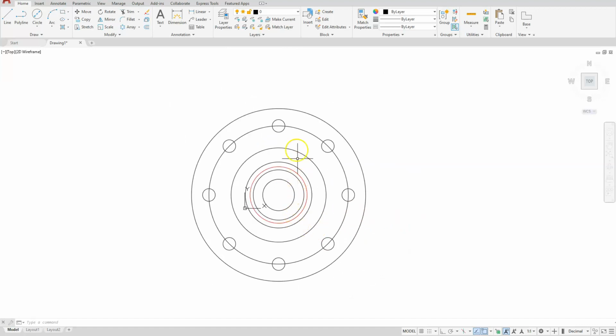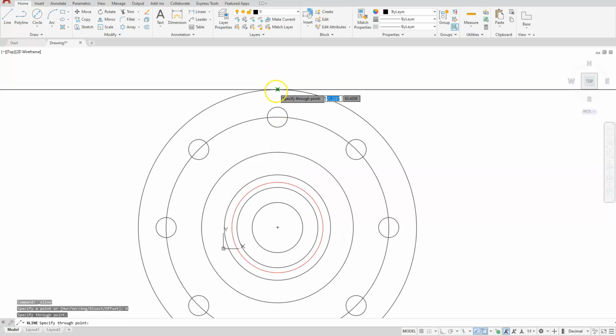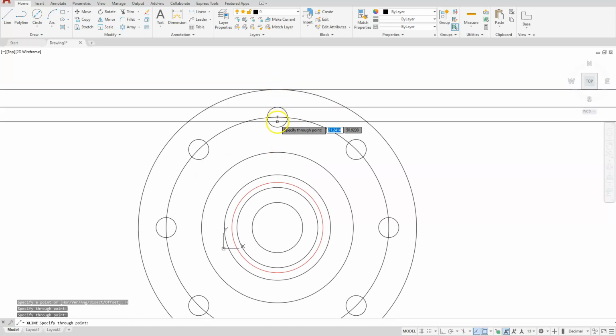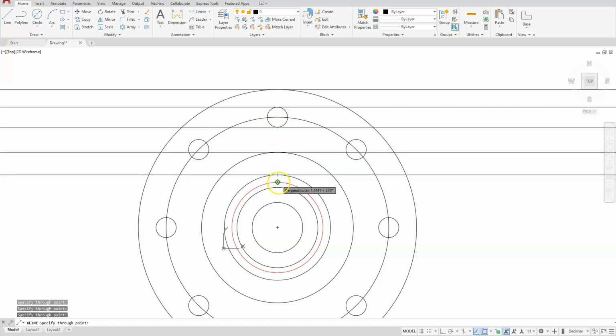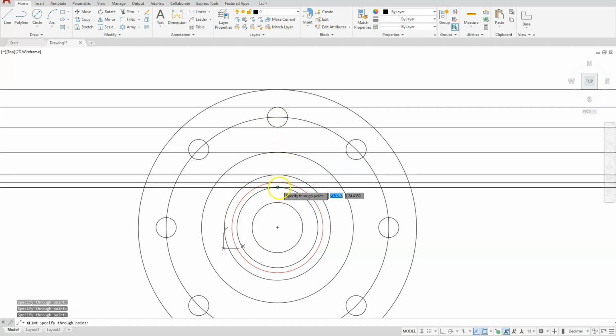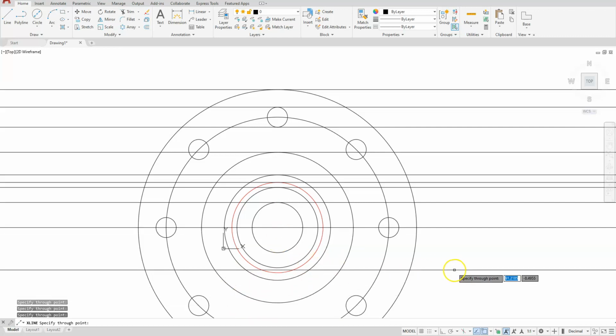This thing is symmetrical. You can see that this circle is in line with this one and so forth. So I'm going to create half of it, and then I can use the mirror command to create the other part. Let's start with a construction line, horizontal. And what I'm going to do is start at this top quadrant. I'll keep clicking the quadrants going down. I'm purposely staying away from the center. I just only want to deal with the quadrants. And this will be the only center that I will select. Here is the bottom portion of my shape.